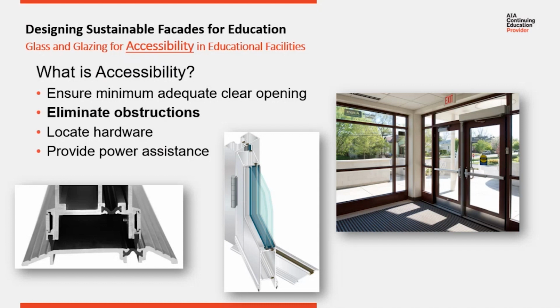Looking at this entrance in the picture on the right, you can see the door on the right has a power assist operator. Mid-rail panics secured to a removable mullion. Tall bottom rails on the door match the adjacent side light. ADA requires a bottom rail of 10 inches so that a wheelchair entering through the door does not get snagged on any part of the glass or the frame. You can see an example of a thermally broken threshold here. Even with the thermal breaks introduced, they are still less than ½ inch.